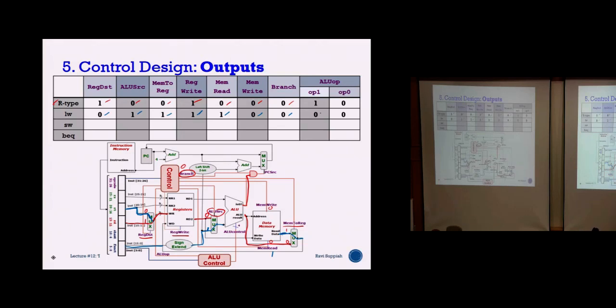And this one, 0, 0, we know from your ALU op. So you must know how to take an instruction and figure out which control lines will be set, which multiplexer will have what value, and so on. So the rest you can go through and see. But you can see there are some of it which is X.